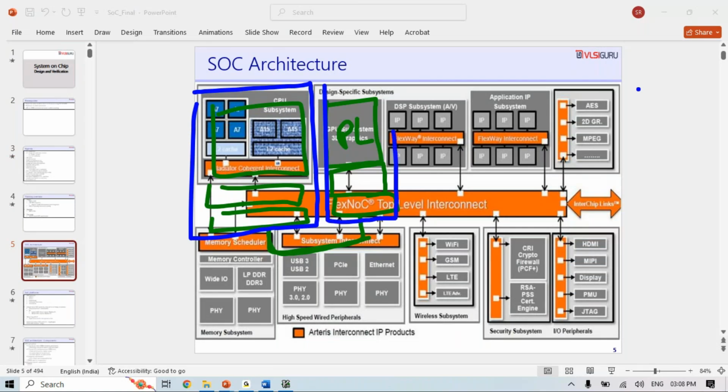Someone who is manufacturing this GPU subsystem as a UCIe chiplet will implement the entire functionality into the protocol layer. They will have the die to die adapter layer and the physical layer. The physical layer has a few more things, something called a sideband link, along with the main link. Here also there is a sideband link and main link, and they will be connected with each other. Like this, various connections could be implemented.